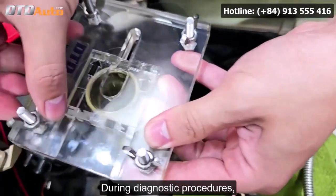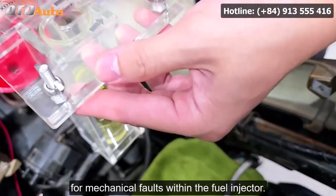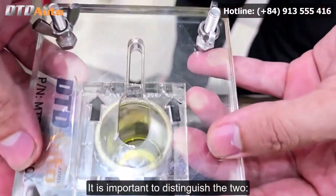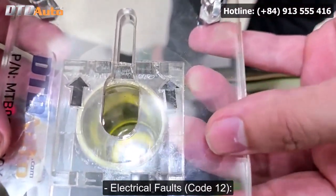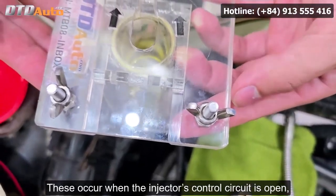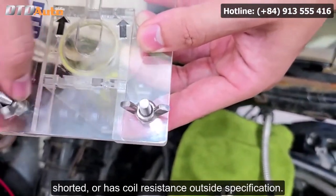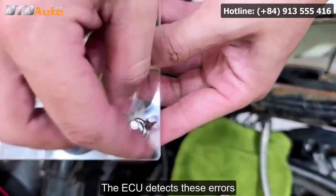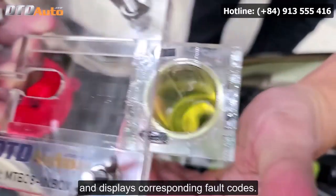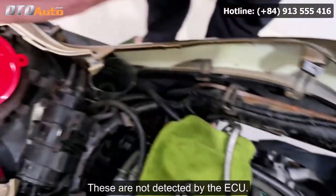During diagnostic procedures, many technicians may mistake electrical faults for mechanical faults within the fuel injector. It is important to distinguish the two. Electrical faults, code 12. These occur when the injector's control circuit is open, shorted, or has coil resistance outside specification. The ECU detects these errors and displays corresponding fault codes. Mechanical faults. These are not detected by the ECU.